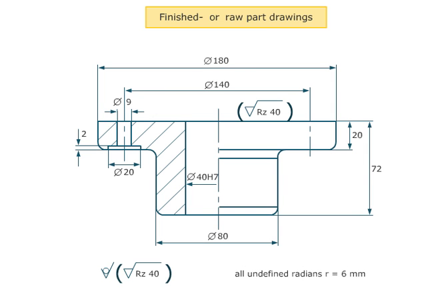As casting processes usually do not allow for high precision and surface finish, the castings must almost always be further machined using a different production process. For subsequent machining, there must be sufficient material left at the positions of the casting where further machining is required to achieve the requested accuracy. Thus, the requested dimensions of the finished part must be greater by the allowance at the casting.